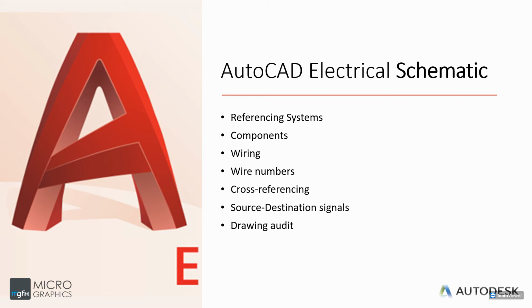Okay, so if you look at your drawing properties, by the way, those formats, those styles, the connection points can be changed from here. So for example, what I was talking about there, these circular connection points, the style can be changed from loop or solid or gap, for example, if you prefer. I prefer the loop, and same here with the connection for joints. Okay, I prefer dot as well.